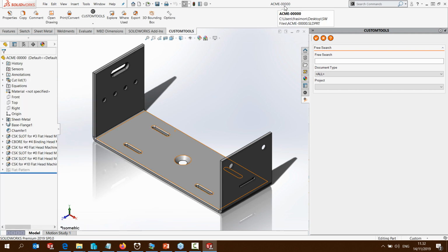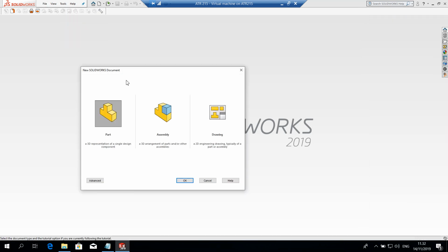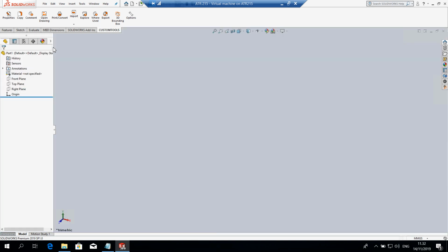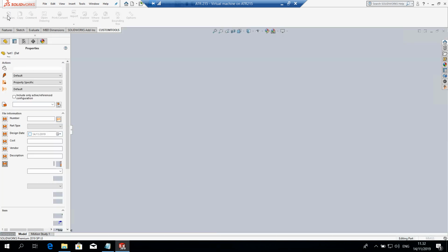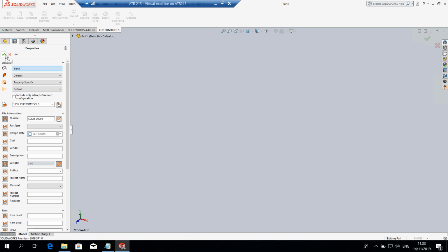And if now a team would start also to do the design, it would have exactly the same thing. So I could go back to SolidWorks and I could now create a new file here. And I will show you that the sequence numbering is automatically going to pick the next number. So if I go to the properties, we can see that we have exactly the property pane that was created, the same profile, and if I just generate the next item number, I have the next item code that was automatically generated, and if I would click OK, the file would be saved.